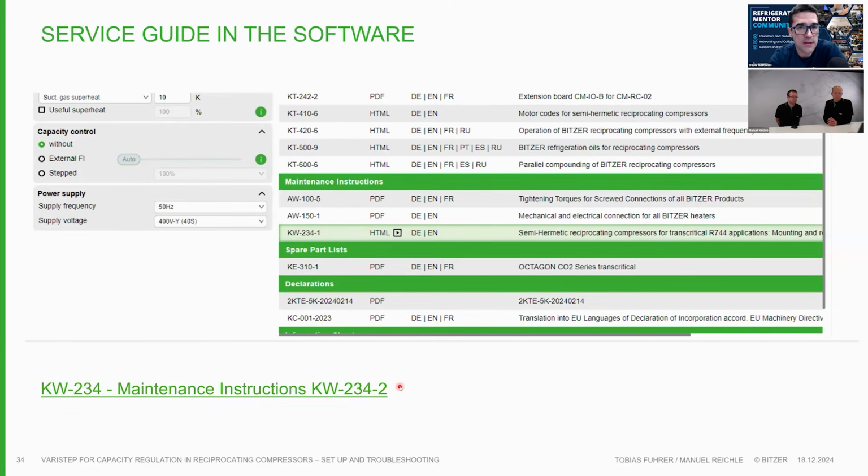For example, these are unloading compressors. When you're at 100% capacity and checking the amps, the amps are going to be the highest, depending on those conditions, your suction and your discharge. But when it unloads, all of a sudden you're going to notice those amps drop off. There's no linear relationship with this because it all depends on the conditions of your suction and your discharge. Do you want to talk about 4 or 5 things that they can check to verify that the compressor is running properly?